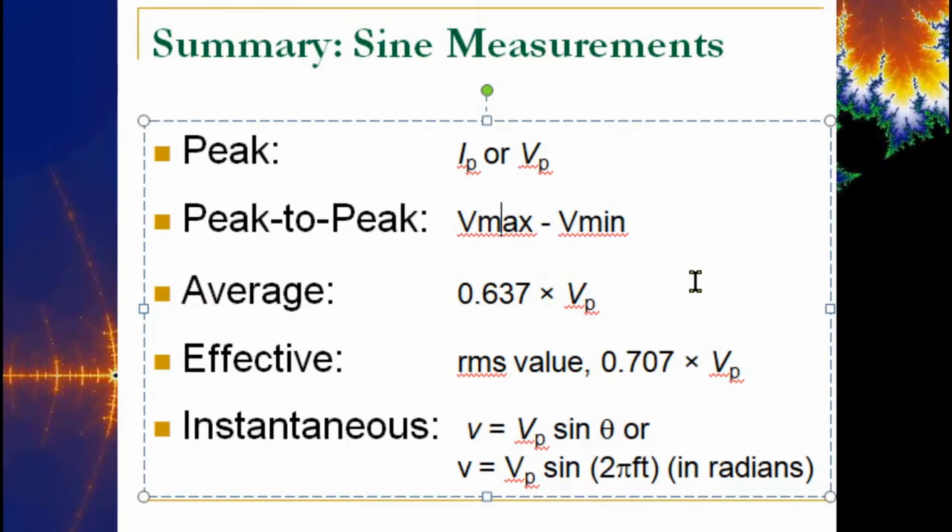Okay, so this one does 1,000 volts category 2, 600 volts category 3. So if I were in industry, if I were an electrician working with high voltages like that, I'm not using anything less than a Cat 4. If I'm doing the lab work that I used to do at the metrology lab, then I'm okay with a Cat 3, okay? But a Cat 3 at 1,000 volts, not a Cat 3 at 600, because I could still